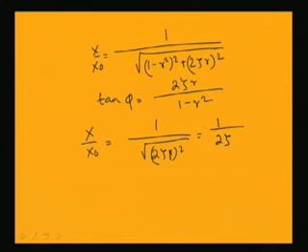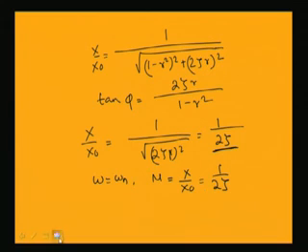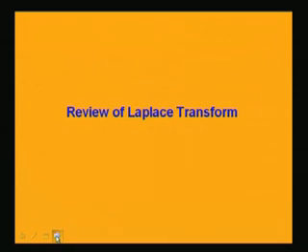So, when omega equal to omega n, then the response of the system is dominated by, or is reduced by, damping only. So, at omega equal to omega n, this magnification factor M equal to x by x 0 equal to 1 by 2 zeta. Now, one can use some other method, that is the Laplace transform method, to find the response of the system.